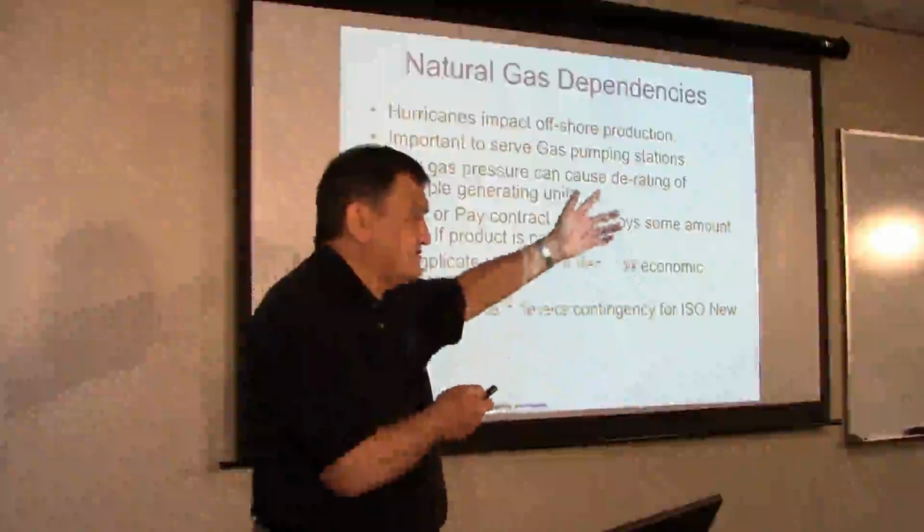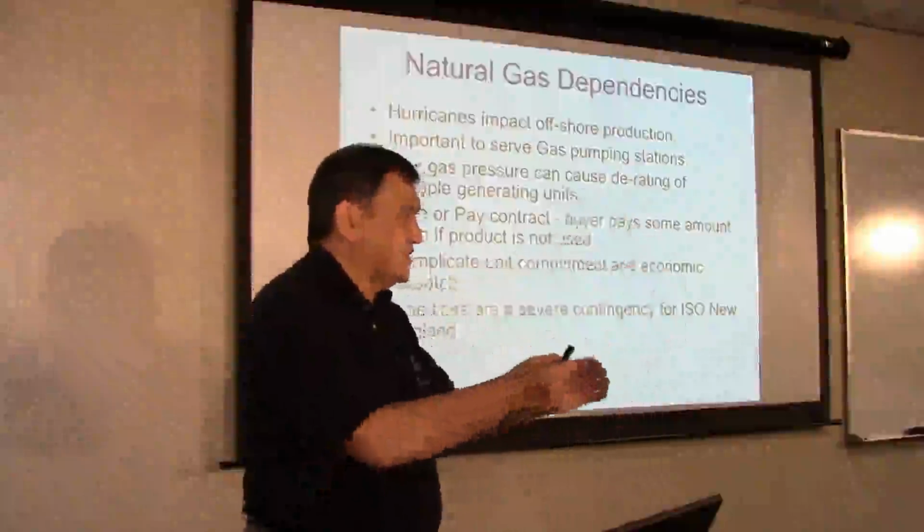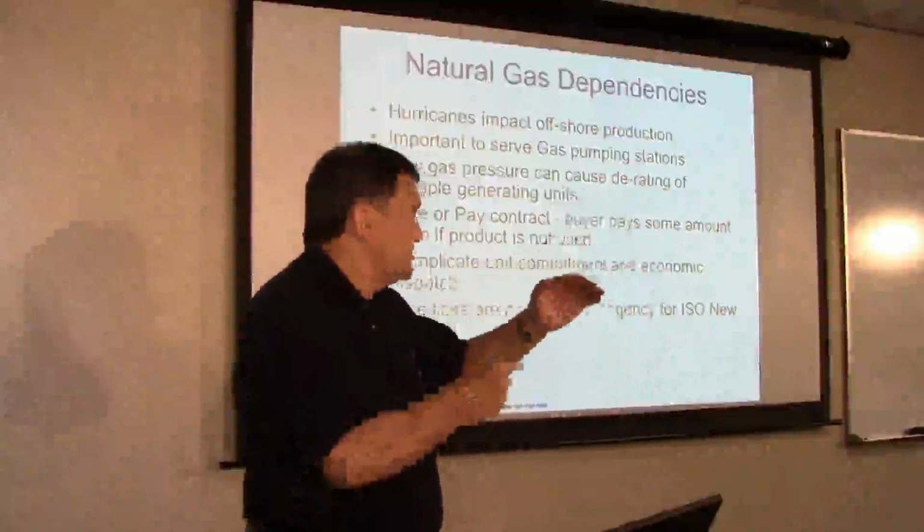You have to say, if I make this decision to use this amount of gas now, and I have this policy based upon my load and my expected demand, how much am I going to use over the next month to make sure that I do either use all the energy that's available or not make an assumption of using too much. And so there are some similar constraints there to hydro units. With hydro, you have a fixed amount of energy constraint as well as the actual constraint of your capacity.